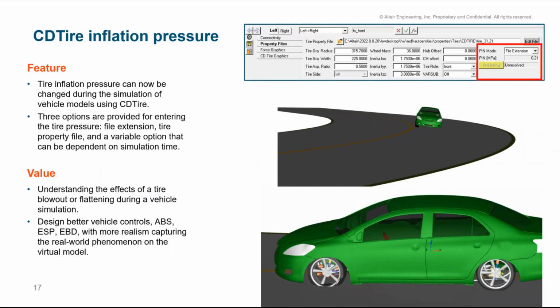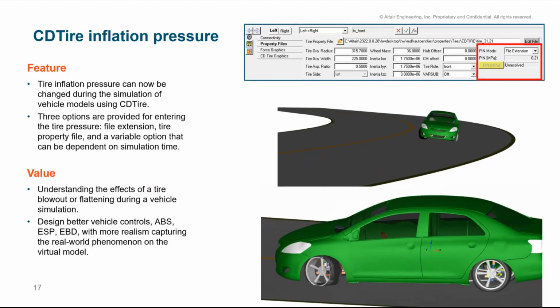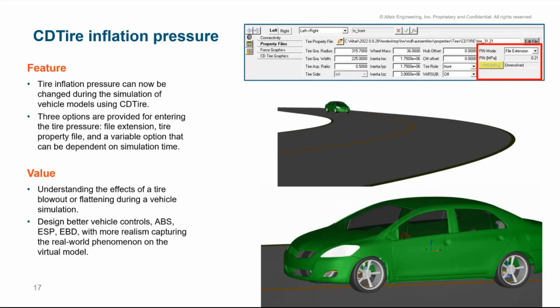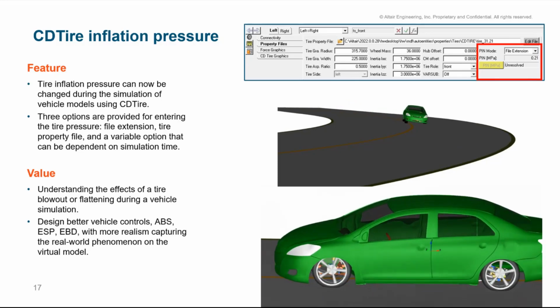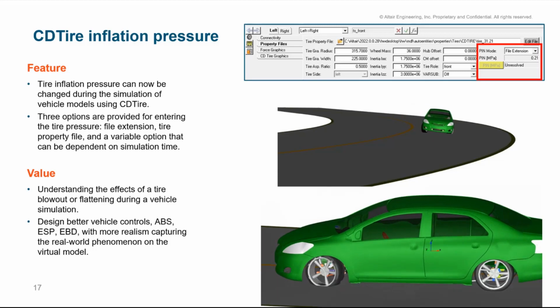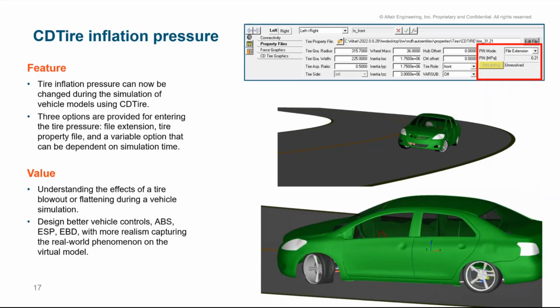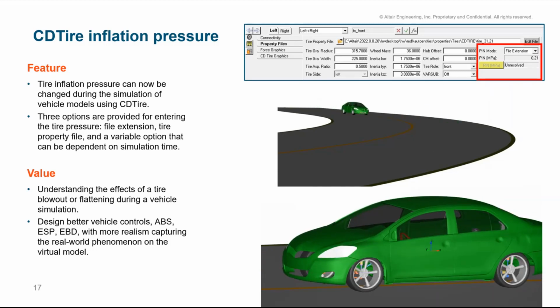Another enhancement is the ability to change pressure for the CD tires mid-simulation. Now this allows you to simulate scenarios such as a tire blowout and investigate how the ESP or ADAS would handle such situations.